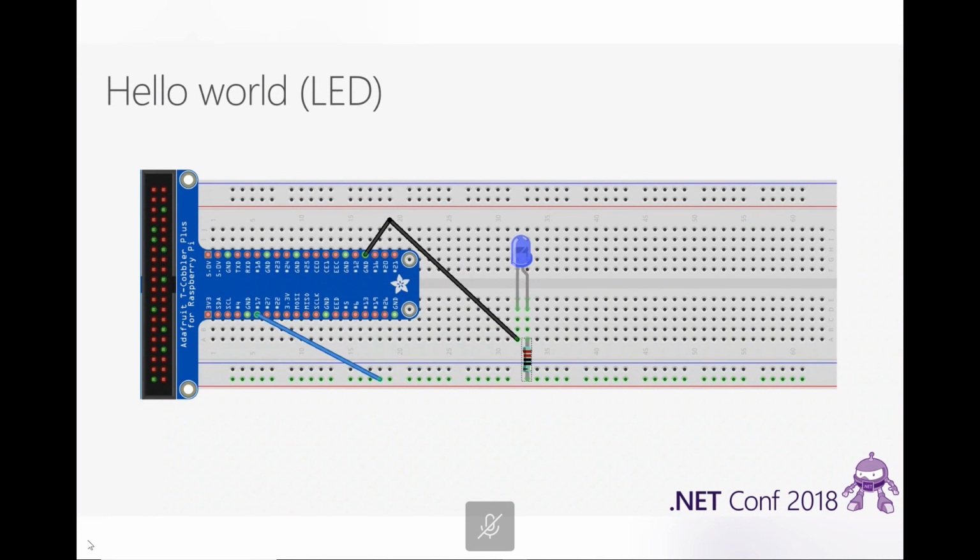So the Hello World app, when it comes to GPIO, is blinking an LED. To do that, I'm using a few devices here that I want to make you familiar with. The first one is this little blue thing right here. On my device, it's black on one, and I think it's green on another one, but it's called a cobbler or a breakout board.